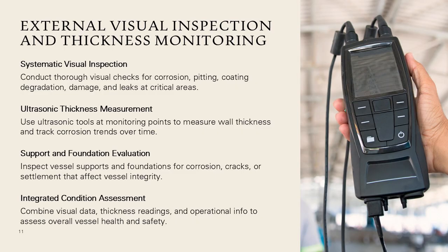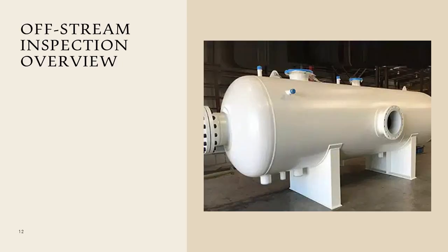In addition to direct examination, inspectors should evaluate vessel supports and foundations for corrosion, settlement, or cracking, as support issues can lead to misalignment and overstress. Combining visual observations with thickness data and operating information allows inspectors to develop a comprehensive understanding of vessel condition during service.